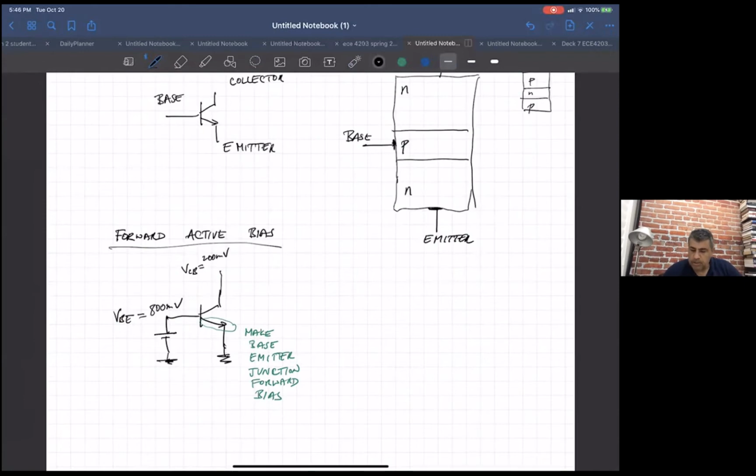But let's say in the lab, if you have a voltage source, you'll be connecting it to the ground. What you'll really be connecting to this guy is a voltage like this to the ground, so it looks like a collector emitter voltage. If I make that, say, 1 volt, because I get 800 millivolts at the base compared to the emitter, it'll make this junction, the base collector junction, reverse bias.